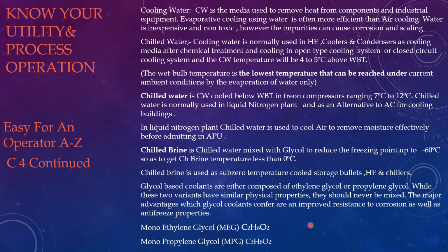Liquid natural gas is regasified in Gulf countries using seawater, whereas in other countries coolant is used. MEG is mixed with DM water and used as a coolant, that is, a chilled brine for regasification of LNG. Hope you understand this important terminology starting with C in this slide. We'll see more in the next slide.